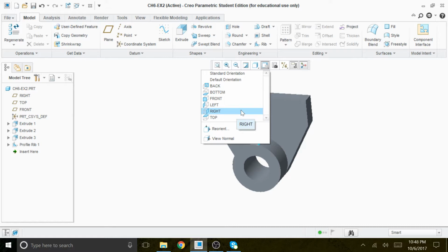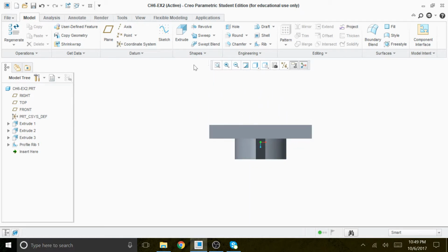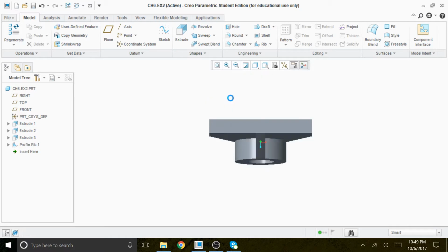You make that decision. For beginners, you just look at the book assignment to see if they are showing two views, and then be a judge. You judge yourself: the reason is that the third view, if I add it, is not going to add any more information to the solid model. It doesn't describe the solid model with more clarity. All right, so when I say top, see that it's going to show top. If I just click on the front view, that's my front view.